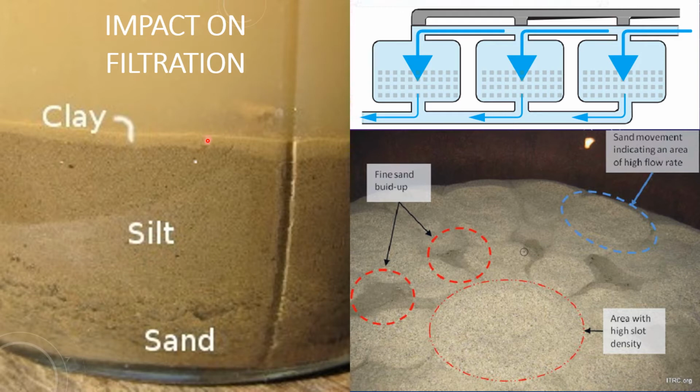And the first point I want to make here is this media in the media tank is the same specific gravity of any sand that might be coming in. So if you have a sand issue, you definitely should have some type of pre-filtration to stop that sand from coming in, because it mixes or infiltrates with the bed. It's very difficult to backflush this out, and actually you'll backflush a lot of your filter media just to get that out. But let's look at it in context after that caution. This is our media bed.